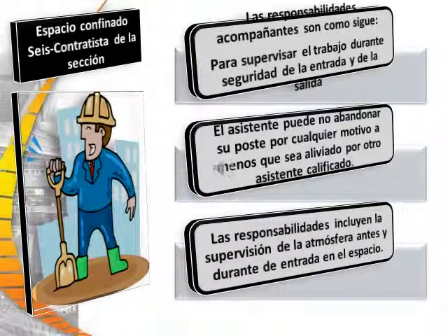Attendant responsibilities are as follows. To monitor the job during entry and exit safely, the attendant may not abandon his or her post for any reason unless relieved by another qualified attendant. Responsibilities will include monitoring the atmosphere prior to and during the entry into the space.